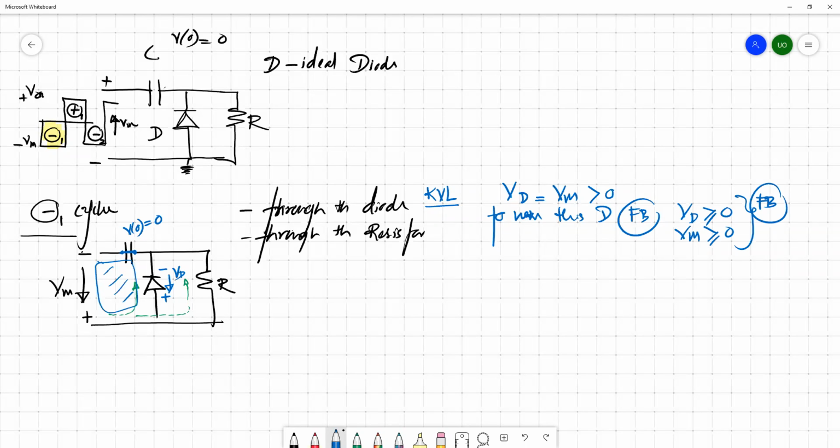If it is an ideal diode, we know that the diode can be replaced with a short circuit element. Now this diode is forward bias, and it acts as a short circuit element where the resistance is pretty much equal to 0. Short circuit means the resistance of that particular component is pretty much 0, or you can say that it's exactly 0.